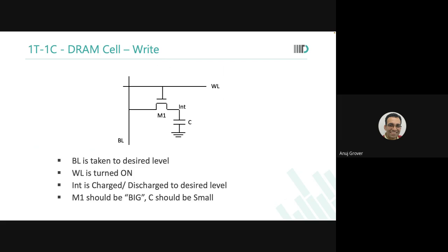But what we definitely understand is that something needs to be given at the memory cell level. You are going from an SRAM to a DRAM to gain density. If you need to use a big capacitor, something has got to give. So the main reason why you were switching from an SRAM to a DRAM is getting eroded in some way.